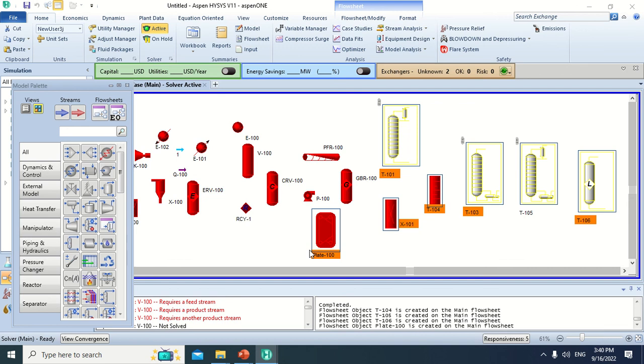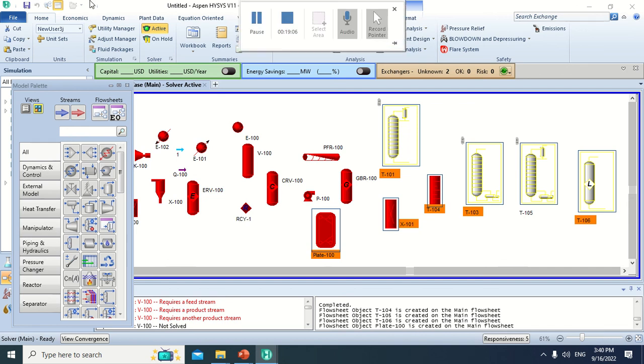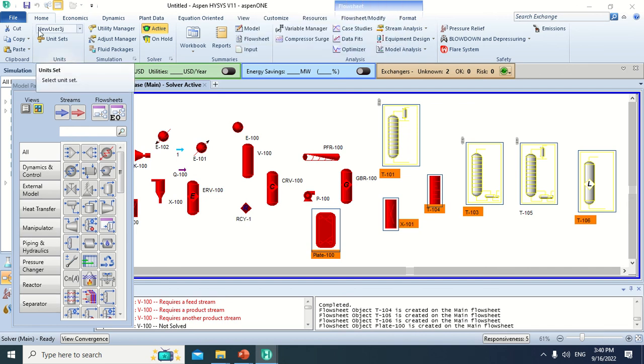Plate exchanger. This exchanger consists of thin plates that are connected with a distance of about 3 or 6 mm, and two heat exchange fluids flow between the plates one by one. We can screw or solder when we connect the plates.